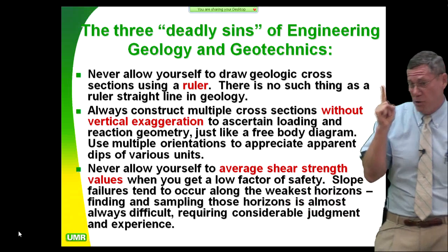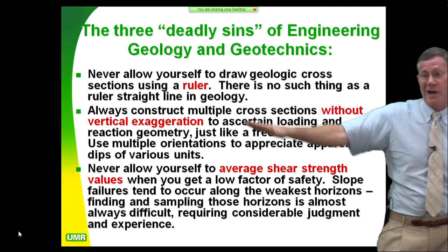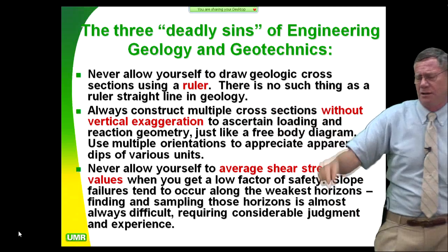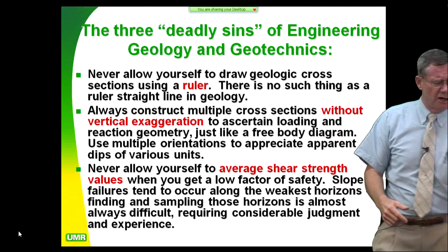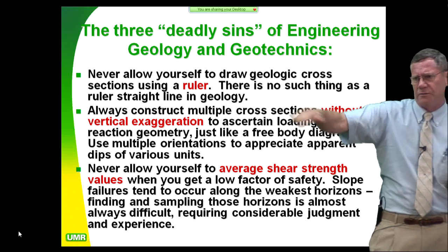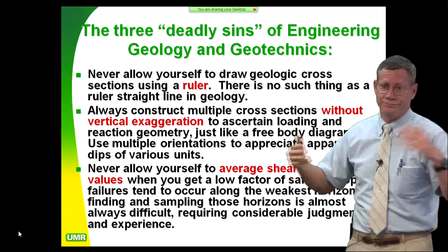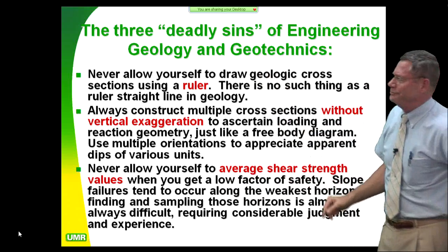Because what you're going to find out real fast is you don't got the wedge out there you thought you had. You got water or air. And that's where you get into trouble. Guys that use charts that are assumed, they don't realize it. Those charts were developed for level front fill, level back fill. Then they apply it to a slope situation. They're going to get the wrong answer.